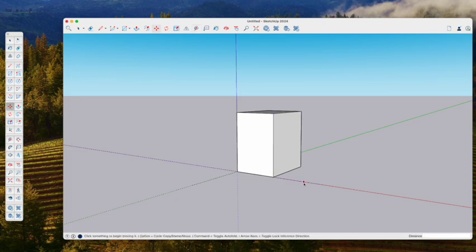I'm going to click the move tool. I've shown this before. I'm going to move this line. See how that arrow or the line there is green? Here it's black. There it'll be blue. Should be able to make it red. It's not really going to change anything, but that's where you're moving in space. Here you're moving in the same plane, and that's what we want to do. We want to move it along this axis.